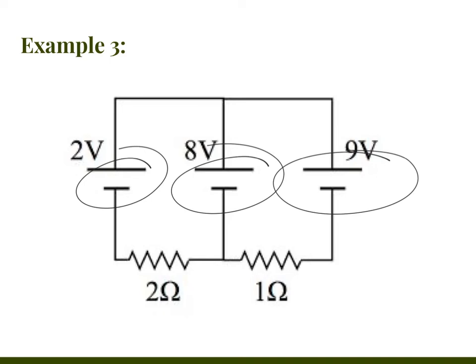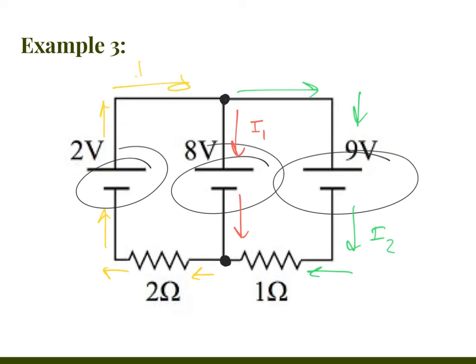So the first thing you do with Kirchhoff's laws is draw your junction points, label some currents. I'm going to actually make my currents different colors here, to help us out. Here in the middle, we're going to have I1 going around this left side, and have I2, sorry, that was the right side, and then going around the left side, I'll have I3. Again, these directions are arbitrarily drawn. You could draw them whichever direction you prefer, but that's the way I'm drawing mine. If I get it wrong, then I'll get a negative current and I'll know the arrows should be switched.